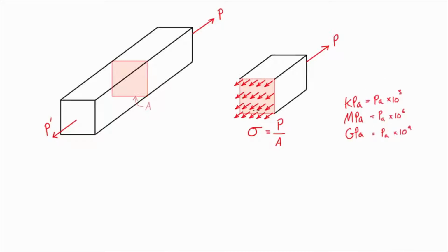In mechanics of materials, we're going to make an assumption to simplify the analysis that there is a uniform distribution of the stress over the whole cross-section of the member, no matter where we slice it. Now, in reality, the closer you get to an applied force, the less true this gets. If the applied force is right at this point on the face, then a point over here in the corner isn't going to be under a whole lot of stress, because all the stress is concentrated right around there. But the further you get into the beam, the more evenly distributed it gets. We're going to make the assumption that it is uniformly distributed everywhere through this beam.